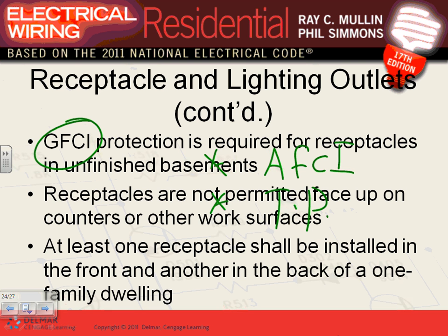Arc fault circuit interrupter, we talked about the places, and GFCI, we talked about where they need to be GFCI. So when you lay out your receptacles, you're going to be thinking, is it GFCI, or is it arc fault circuit interrupter? But you never question that it has to be tamper-proof.